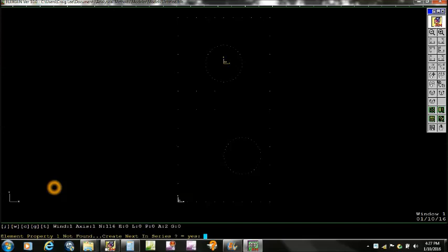And element property, we didn't create an element property yet, so we have to do that. Material property is going to be, we'll just default to 1 here. Turns out that standard material 1 is aluminum, 1100 H18 aluminum, and the thickness of the plate will be 1/10 of an inch. We'll just call it plates for that plate property. And then we'll have a group. We have to define a group that the elements go into. That hadn't been done yet. We'll just call that rectangular plate.